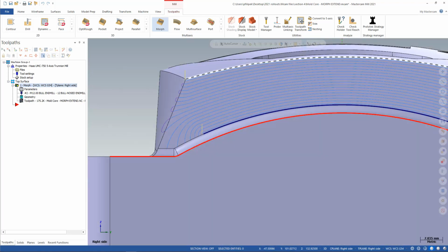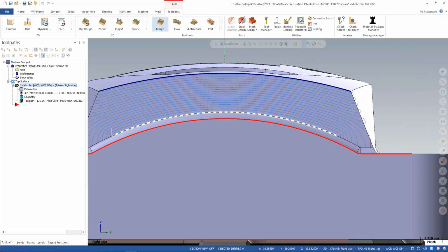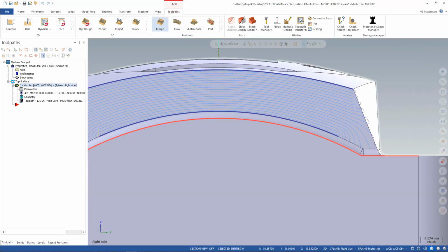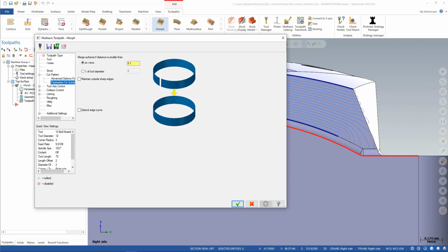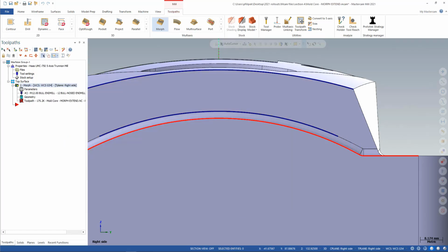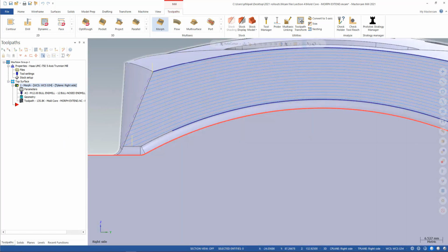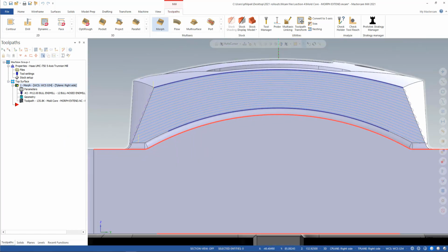It's kind of rolling off, morphing from here to here. Well, over here is a surface, so it has to try to do something with that. And it looks pretty terrible there. It's really a bad cut on these ends. Once again, same situation here. I can come in here to my parameters for surface edge handling, turn on extend edge curves, regenerate this, and now I get some nice flows along there for our tool path, nice back and forth motion along our curves.